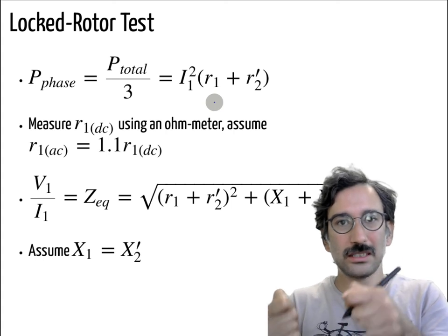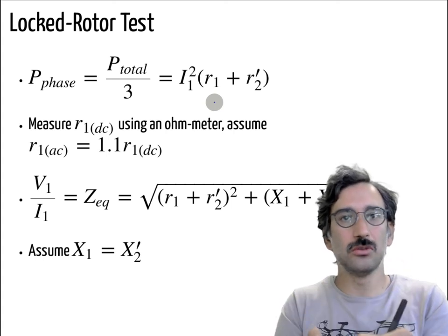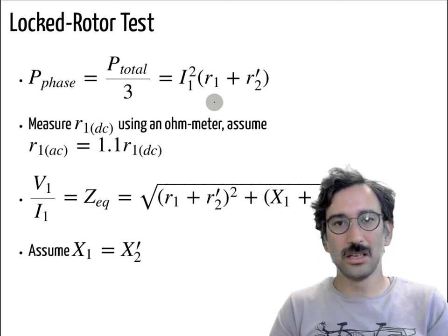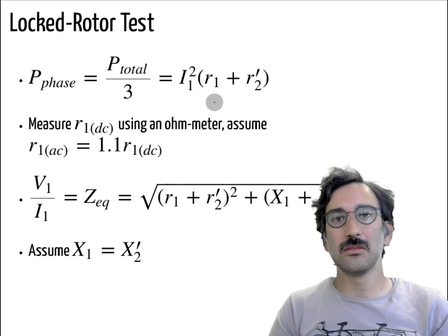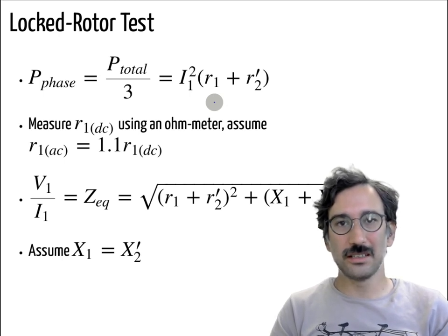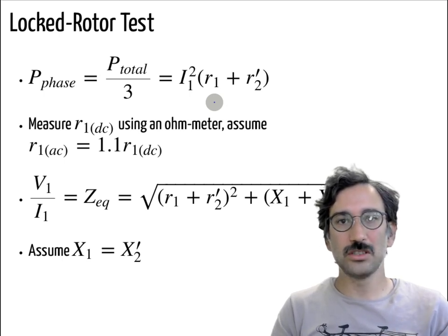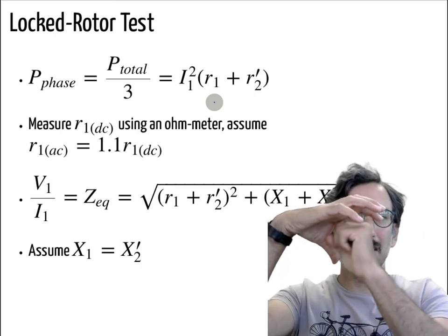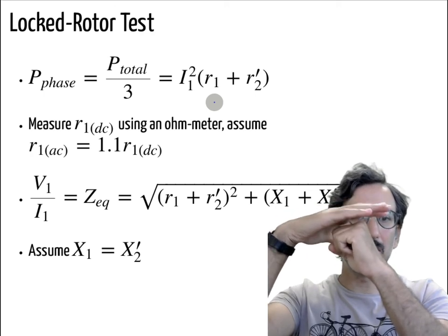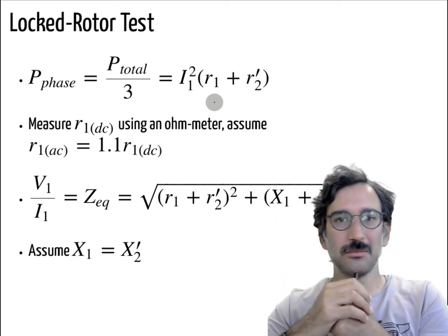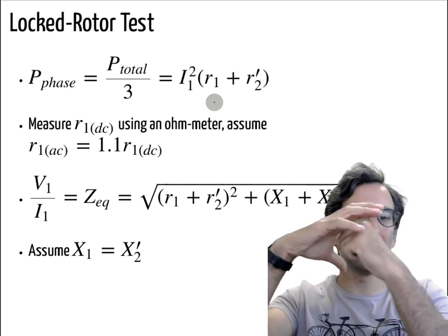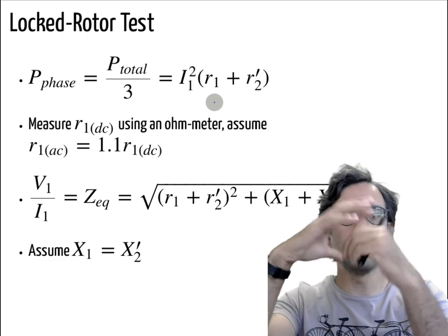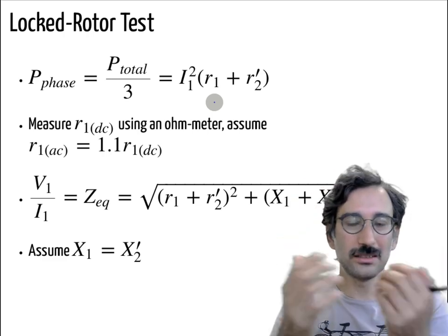If you just connect the ohm meter to the stator terminals, where you have like 3 cables coming out of your machine, you can measure the stator resistances. But you will not be able to measure the rotor resistances, because, visualize the rotor and stator, they are not electrically connected, there's an air gap. That was the main advantage of an induction machine: there are no brushes, nothing to connect electrically to the rotor. All the power is transferred wirelessly.